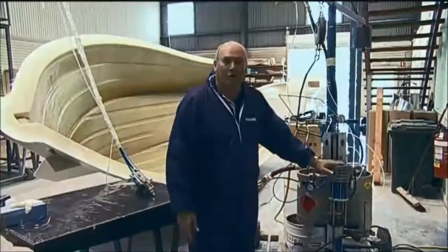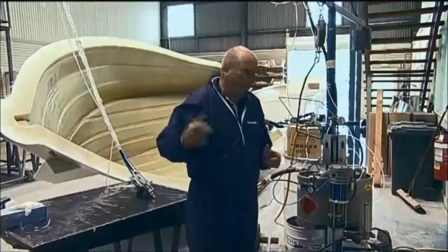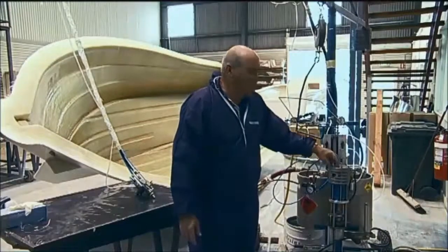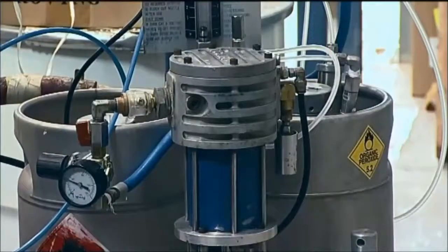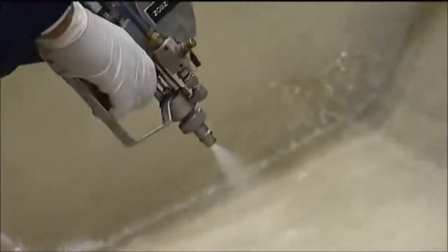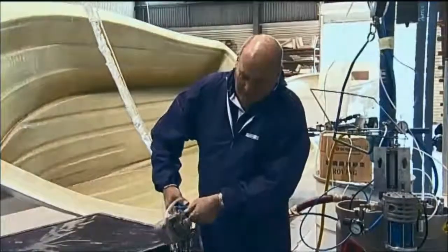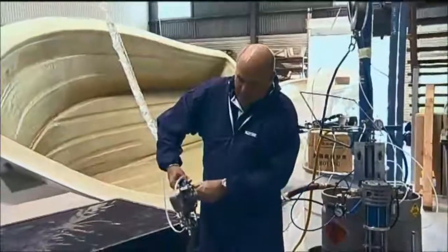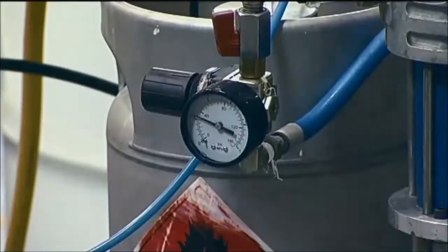So once again, it's a high pressure style delivery gun, and the difference between that and the gel coater is it is a slightly lower ratio for pump pressure. We don't need higher pressure with this because unlike an airless system, this is an internal mix gun. Okay, so this means that the resin and initiator is mixed inside the head. So this requires a solvent flush system. You see over here, that's the acetone, sorry, it's the solvent, and that flushes the head. Okay. So this requires a solvent tank.